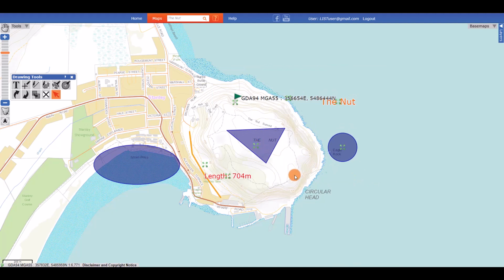You can also duplicate any markup feature in your map. Start by activating the Select Features tool. Then select the feature you want to copy by clicking on it. Then click on the Duplicate Selected Feature tool with the two grey squares and an arrow icon. Your new feature will appear on your map, offset a small distance up and right of the original.